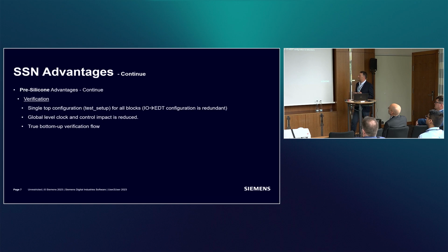On the verification side, we have only one test setup. Previously, we had several configurations of partitions. So we would run 3 blocks together to optimize the EDT channels and find the best solution of EDT configuration between the partitions. Now we don't need that. We have a single test setup, and we can use that for every configuration, so we don't need to reset and load a different test setup each time that we change the partitions or the multiple blocks that we're running together.